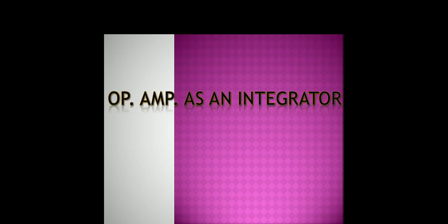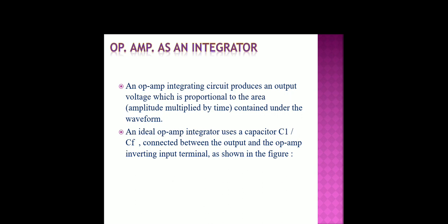Integrator circuits are usually designed to produce a triangular waveform at the output from a square waveform at the input. An op-amp integrator circuit produces an output voltage which is proportional to the area, that is amplitude multiplied by time, contained under the waveform. An ideal op-amp integrator uses only two components, a capacitor and a resistor. Capacitor CF is connected between the op-amp inverting terminal and the output as shown in the figure.